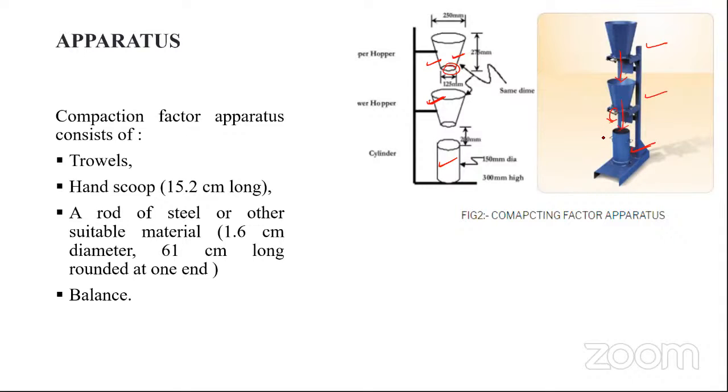During the falling of the concrete, the compaction process takes place. The compaction due to the effect of gravity takes place in that concrete, and when the cylindrical mold is completely filled with concrete, we flush out the extra concrete at the top of the mold and level it.